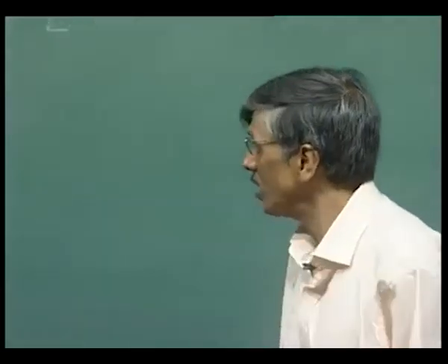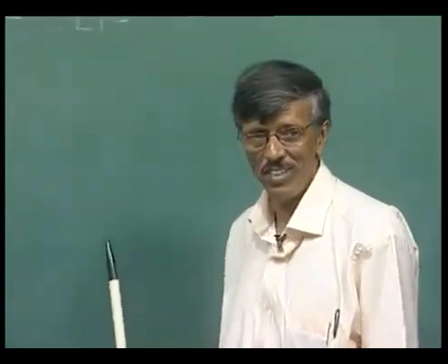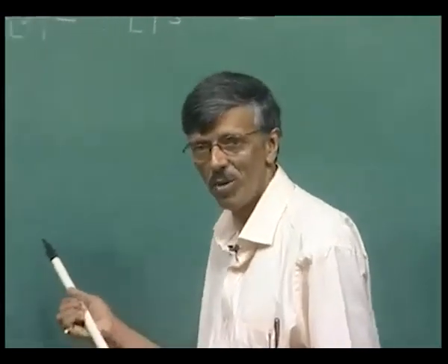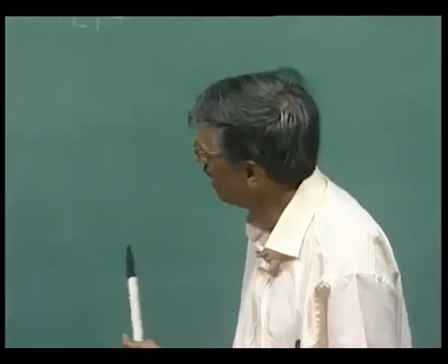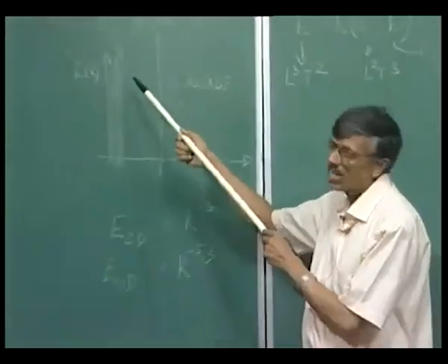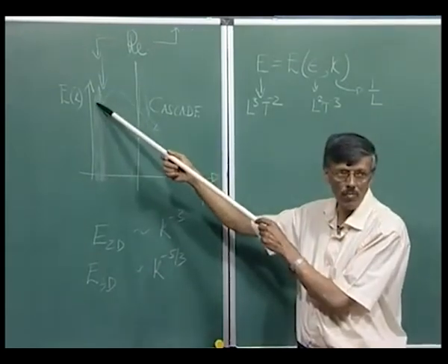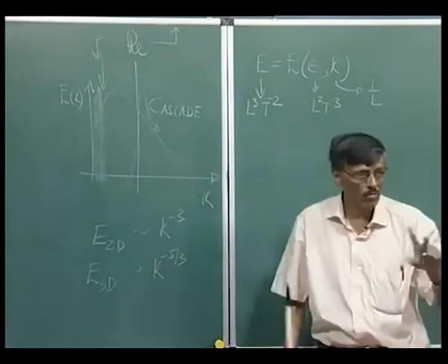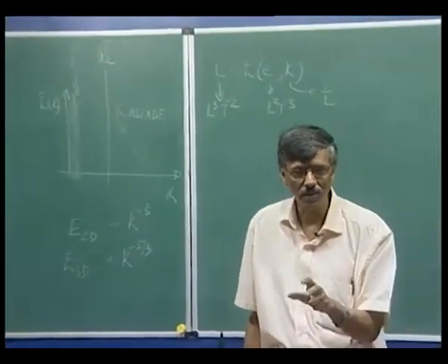Okay. So, now I think we have a fairly decent idea what happens in a turbulent flow, which we get by very little investment. We have mostly depended upon dimensional analysis, and we have said something which is very true, that if we have a statistical equilibrium steady state, then the energy that comes in here cannot reside there because of the role of the nonlinearity versus the viscous term.